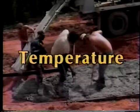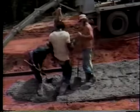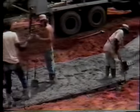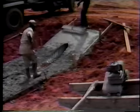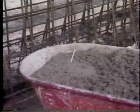Now, temperature. The temperature of fresh concrete affects the rate at which concrete gains strength, the amount of strength the concrete ultimately acquires, and the porosity of the concrete. Checking concrete temperature is simple. It should be done according to ASTM C1064.